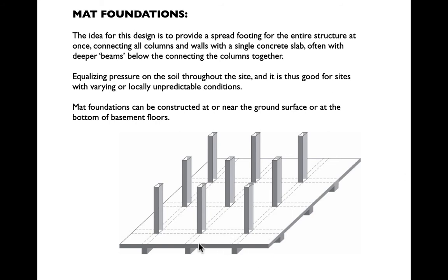The downside is that the slab is now experiencing shear at every one of those columns and bending between them, right? This is literally a reverse floor slab, only now we have the punching shear problem at every column because the whole weight of the height of the building is coming down on each of those columns and giving us really a worst case shear where we're trying to collect all of those loads and spread them out over the soil.